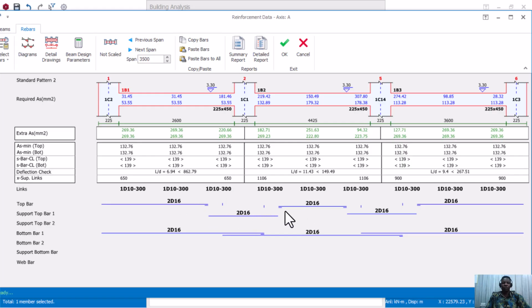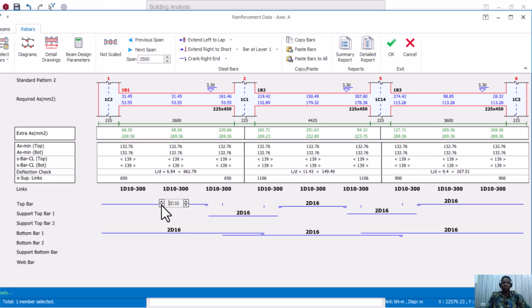So this is 2 rebars for all the sections. In this situation, you can see everything passing. But in some other situation, if you reduce this reinforcement, you can see that there will be failure. This failure must not occur. Especially in this extra area, this is the area provided, and it should be the area required. You have to make sure that everything here does not show anything red. It has to be colored green. So you have to make sure that is okay.